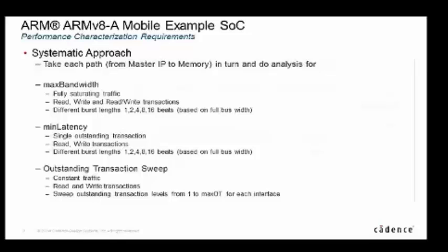And we're able to do this because if you look at the DUT we're talking about as a black box with AMBA interfaces on it, you just need to know what the AMBA configurations are to be able to automate some of this.